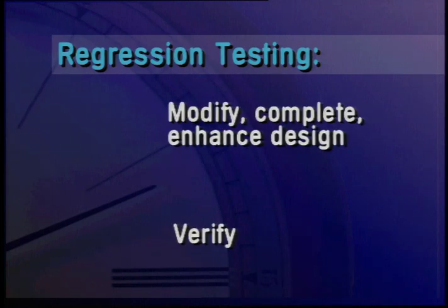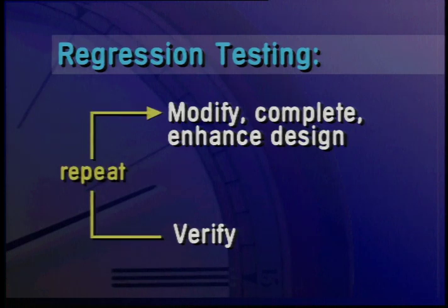In addition, the nature of the logic verification step is iterative. Simulation usually begins in a regular way as soon as the model shows signs of life. Simulation tests, or regression tests, are run continually through the design and verification process. As more functionality is added to the design, more of the test suite is run regularly to ensure that previously working features have not been broken. The model has not regressed. Consequently, not only is the total number of simulation cycles in the set of simulation tests very large, the tests get run repeatedly as the model evolves.